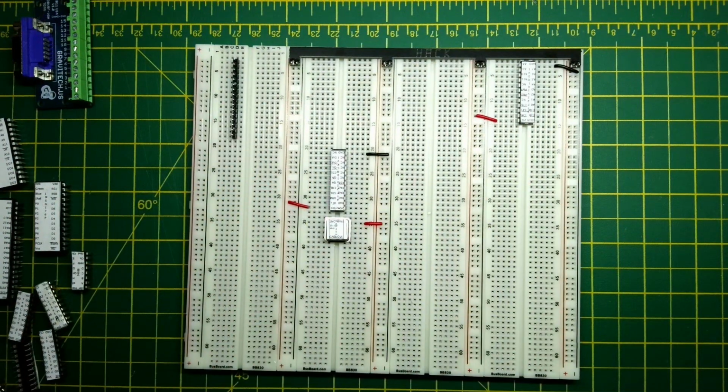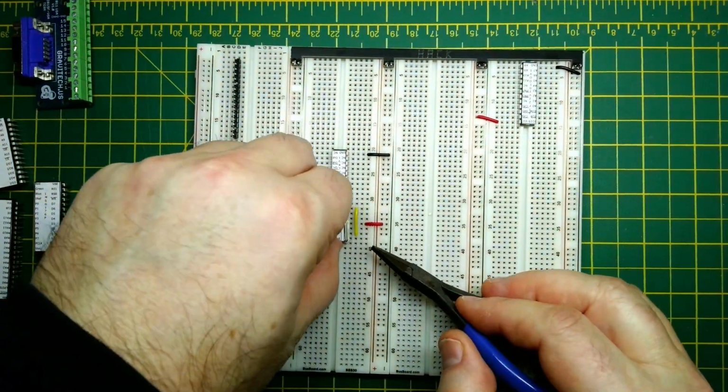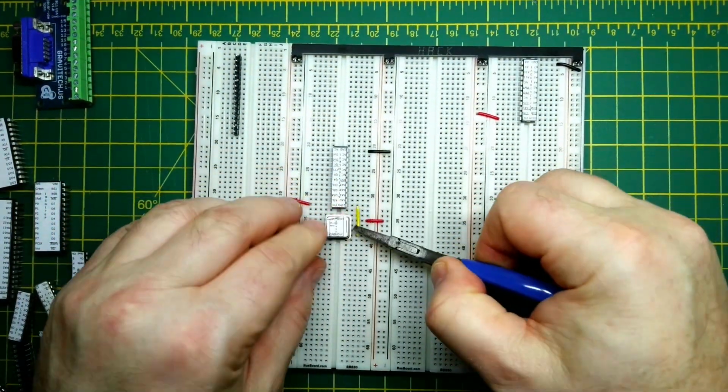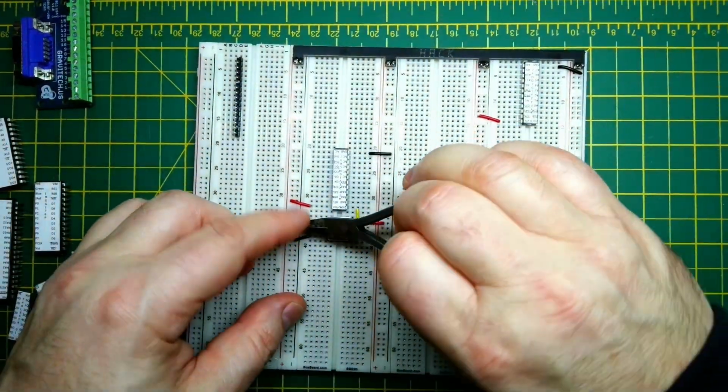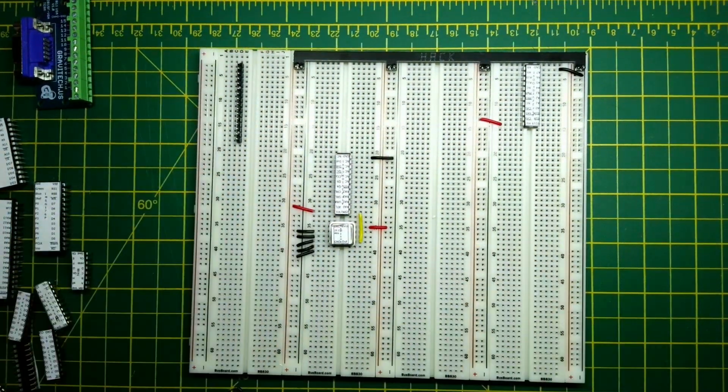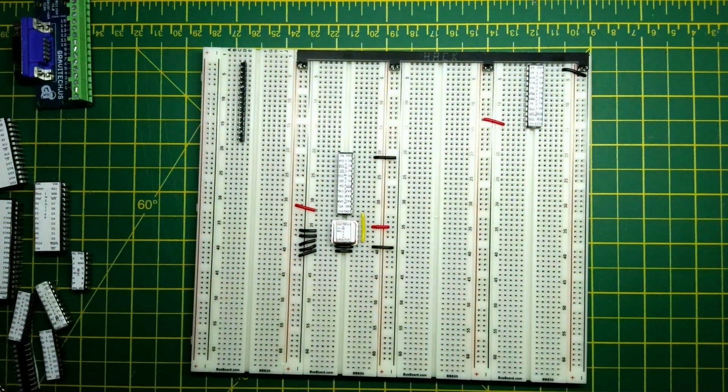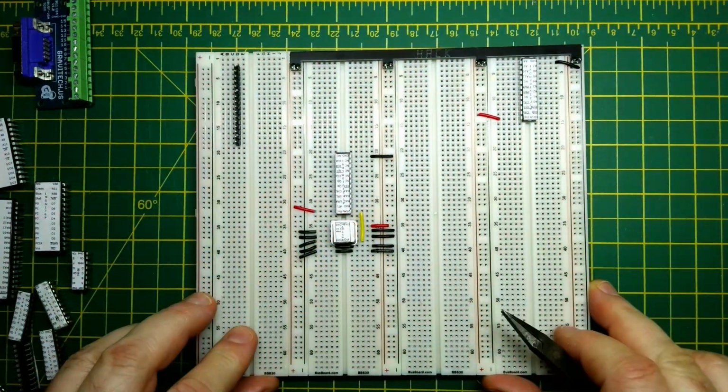And for the oscillator, we're going to wire in the 25 megahertz output and just make sure it's in the right pin. Then we're also going to ground a lot of the leads around the oscillator to prevent any stray 25 megahertz signals getting onto any of the other tracks.